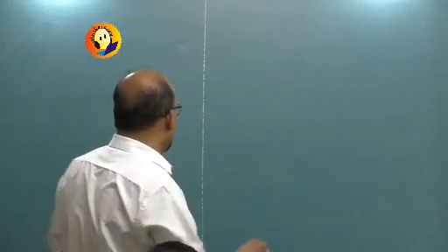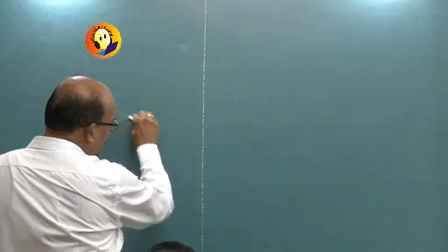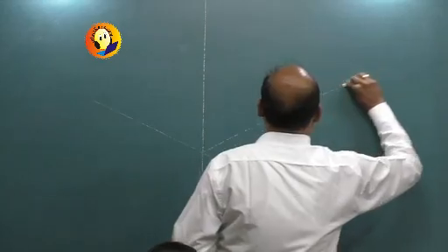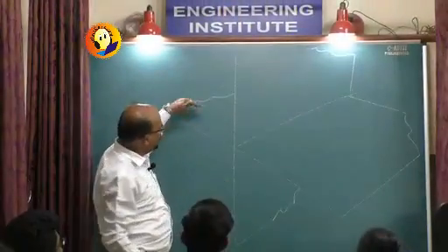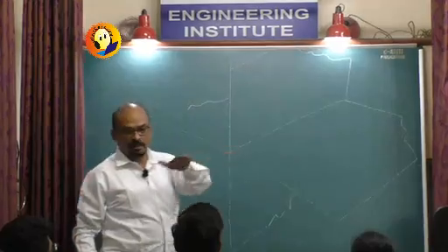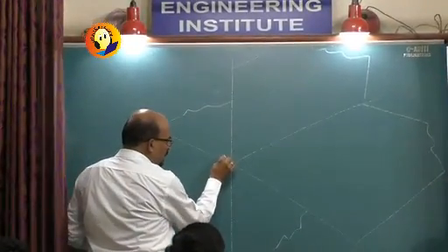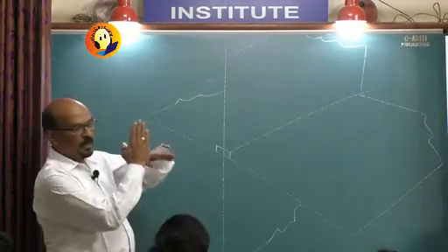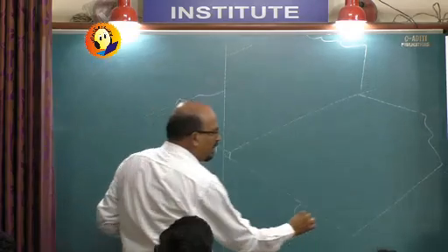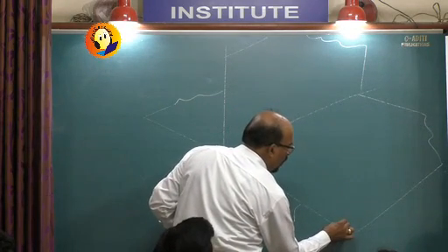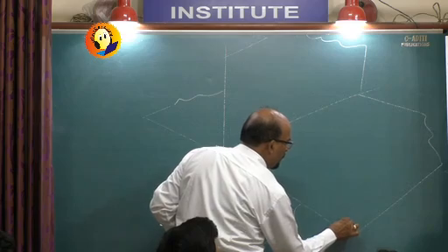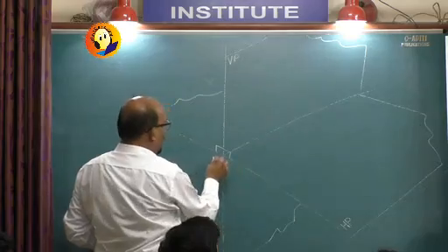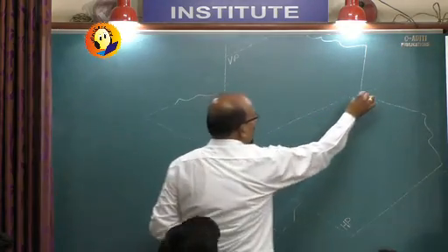But the basic concept is, they say that the entire space be divided into 4 quadrants. Why am I showing them like this cut? Because these are infinite planes. And how are those two planes? Those two planes are actually perpendicular to each other. These are two planes, and these two planes are referred to as horizontal plane and vertical plane, and their intersection is normally termed as the line XY.